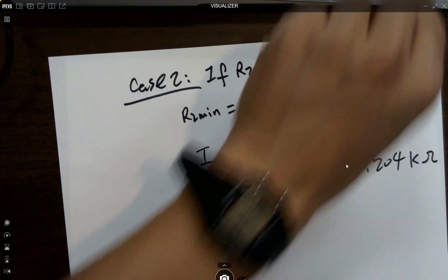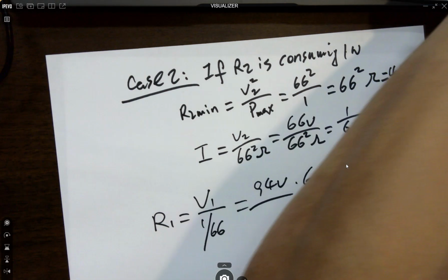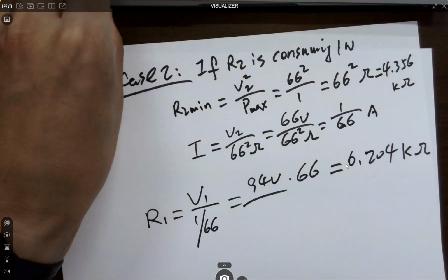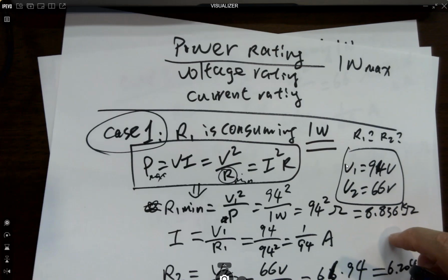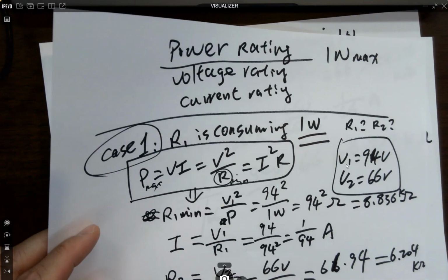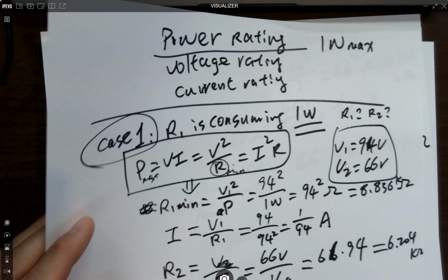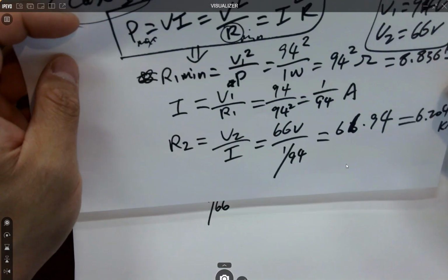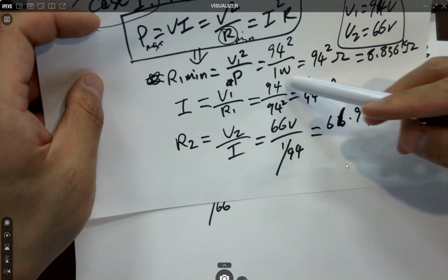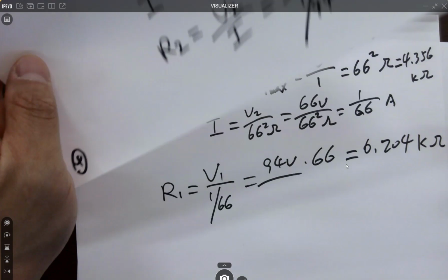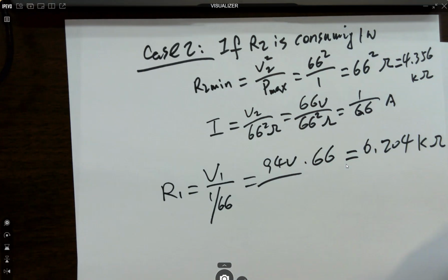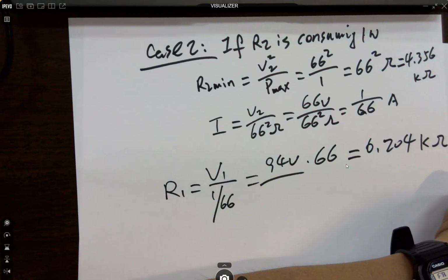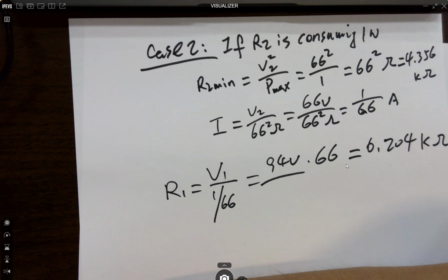I mean, the solution is actually the first one. Solution is this one. So now we can verify it by putting it back, see if it's satisfying. It is satisfying because of this. Let me see, what's this asking? Same current. R1 must be greater than R2 to satisfy the voltage requirement. Therefore, R1 will dissipate more power.